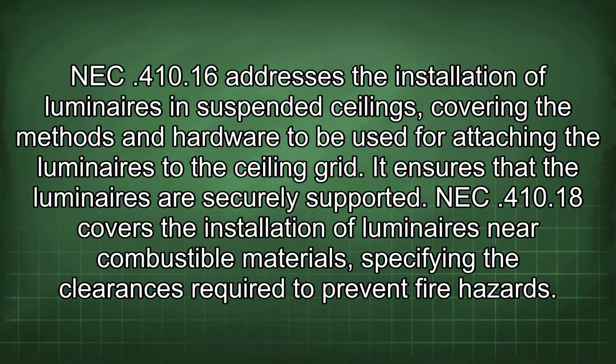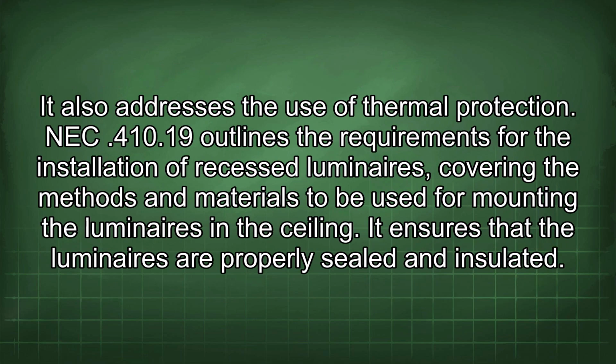NEC 410.16 addresses the installation of luminaires in suspended ceilings, covering the methods and hardware to be used for attaching the luminaires to the ceiling grid. It ensures that the luminaires are securely supported. NEC 410.18 covers the installation of luminaires near combustible materials, specifying the clearances required to prevent fire hazards. It also addresses the use of thermal protection.